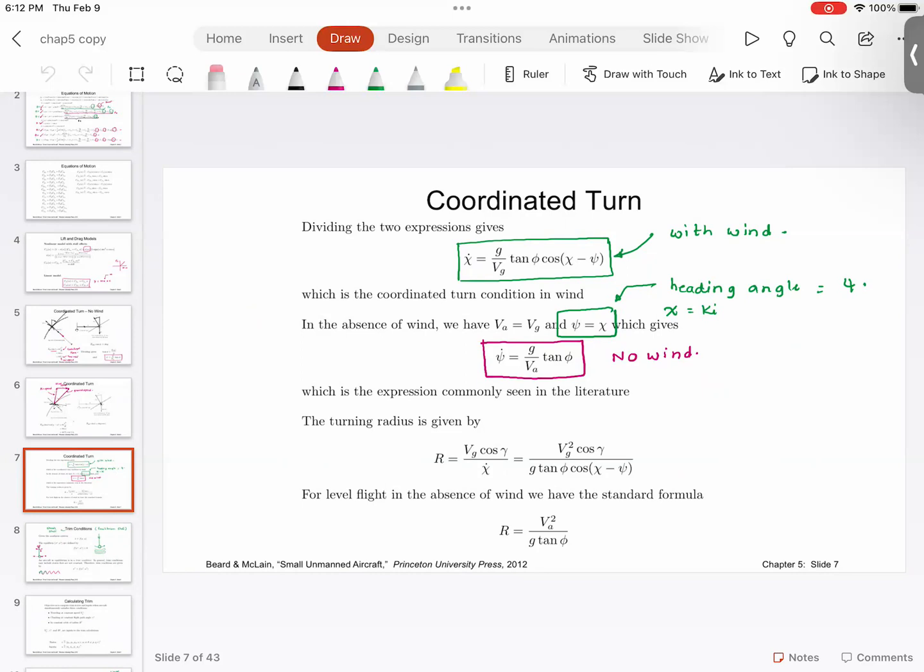And if you use something like an IMU or airspeed sensor, then that is a special flight condition where you have to compensate for the apparent effect measured by the flight control or the IMU. Because please try to understand, when the aircraft is banking, you will notice that in addition to its forward acceleration, it is experiencing lateral acceleration, which means if you were to use the accelerometer, just like the spirit level in your smartphone, you would get a wrong measurement, because right now the acceleration that it is measuring is not related to the true component of gravity. There is a centripetal acceleration component in it.